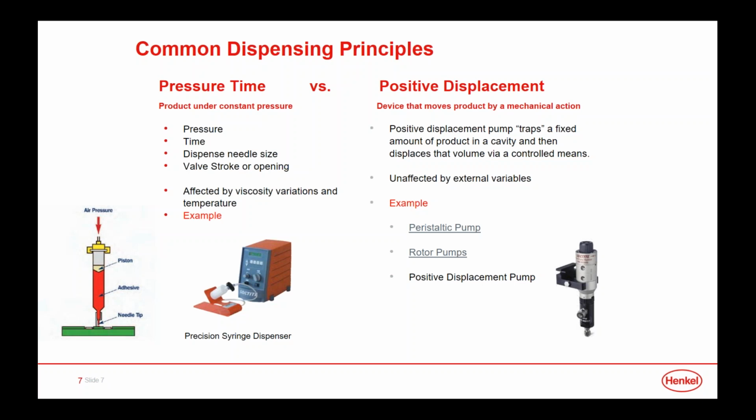For applications that require that level of precision, such as the medical industry, or if there are high costs of waste outside of a process, positive displacement might be a solution that would provide a customer with a much better and much improved process from an accuracy standpoint.